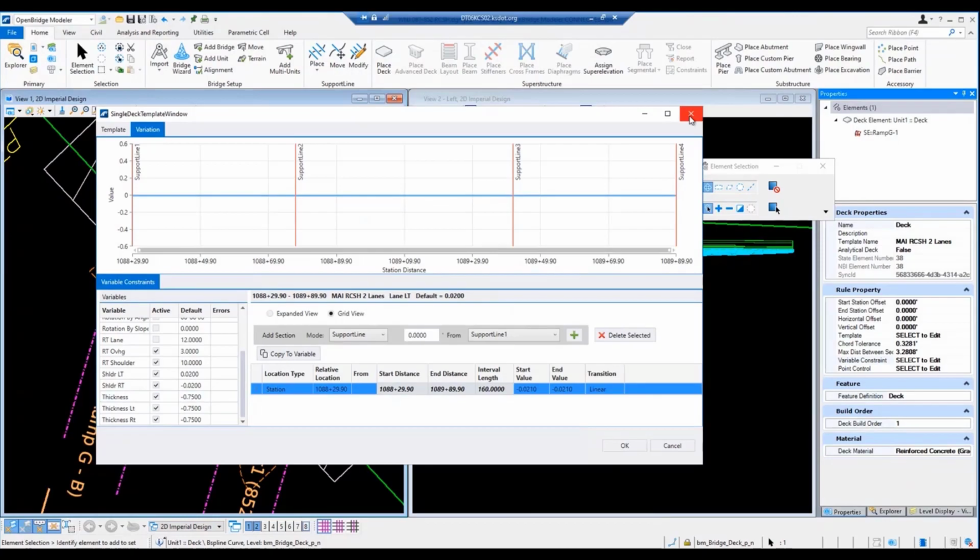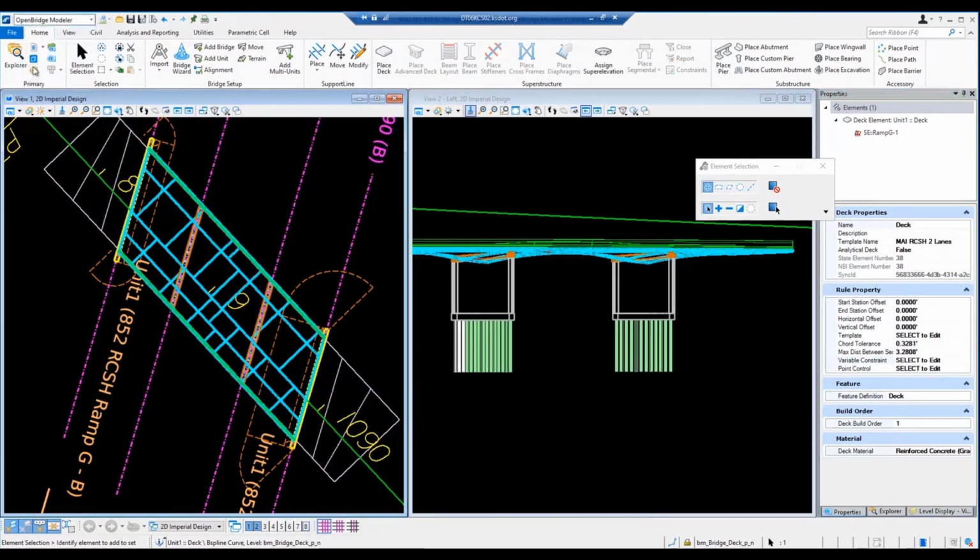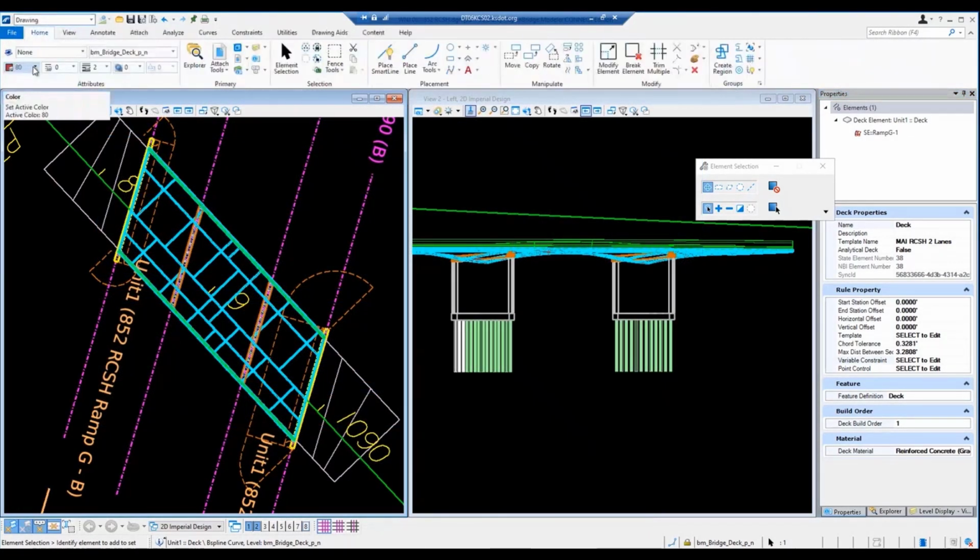In a similar nature, and this is for further discussion for KDOT as well, among all you designers and techs up there, I would be very interested. It's not possible right now to very effectively place a corral rail with the posts. It's very easy to extrude the end post on each end of the bridge and then extrude the rail portion from the interior face of the end post to the end post.